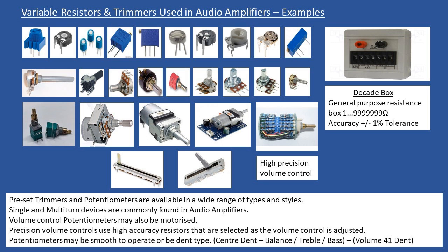And when they design these electronic circuits where you use the trimmers, in terms of design, they tend to aim around midpoint. And the reason why that's important is I don't want to see an electronic circuit where you're on the extreme edge of the trimmer, either left or right of that, so its minimum resistance or its maximum resistance.